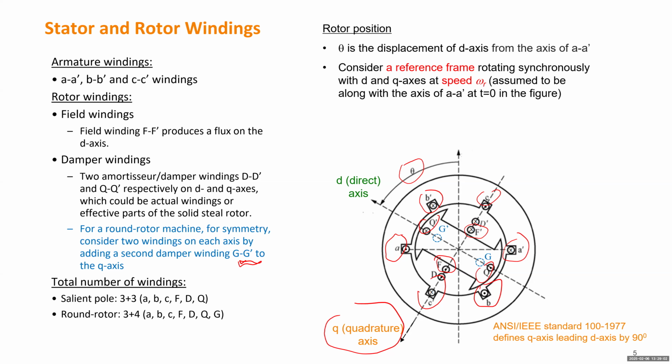But it's not very convenient to categorize the position of the rotor, because in reality, nobody can look inside of the rotor to see where the D axis is really facing. And that's not important at all, because in reality, as I said in the last section, if we talk about rotor angle stability, it's important to have two rotational masses, which means two cylinder generators. If the two angles are always pointing to the same direction, the two generators are synchronized perfectly. But if one angle is separating from the other, and the angle keeps increasing, one generator may become unstable.